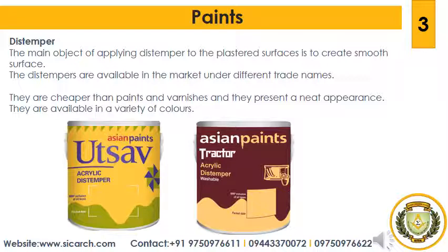The oil-bound distempers are a variety of an oil paint in which the drying oil is so treated that it mixes with water. The emulsifying agent which is commonly used is glue or casein. As the water dries, the oil makes a hard surface which is washable. It should be remembered that most of the manufacturers of ready-made distempers supply complete directions for the use of their products. The directions are to be strictly followed to achieve good results. So that's all about the distemper.